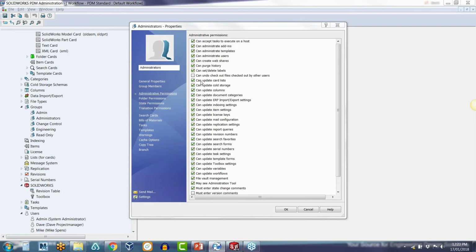It's if the person is on vacation and you really need the file, that's something you can do. The other thing you can do is go on that person's computer and undo the checkout, or check in the file from that computer, and that's also allowed. If you have a different user on the same computer, and you have access to the local computer, you can log in with a different user, then check in or undo the checkout from that computer, and either check in the changes or discard them. But that's basically something that's not reserved for the admin user, which was the case in the past.